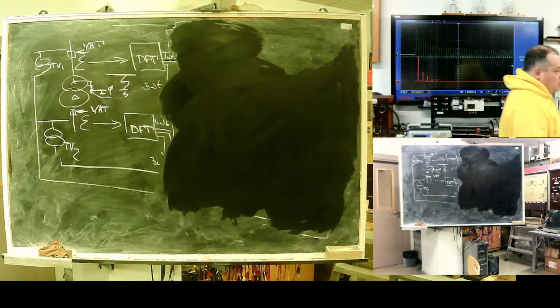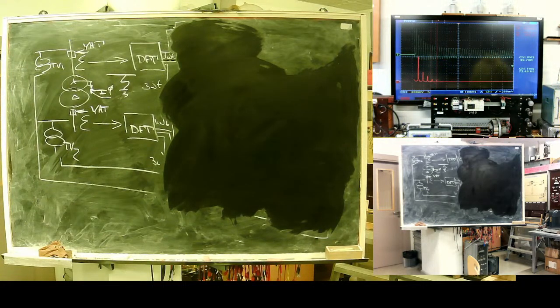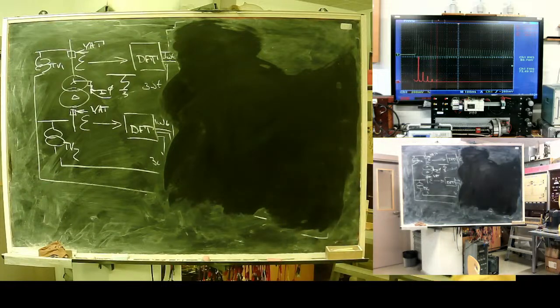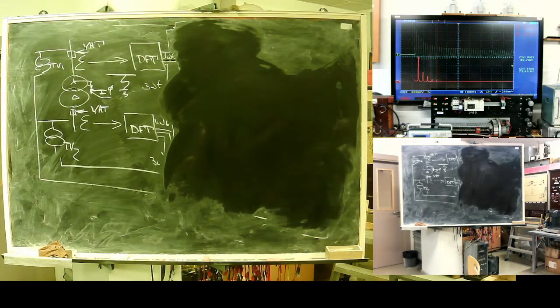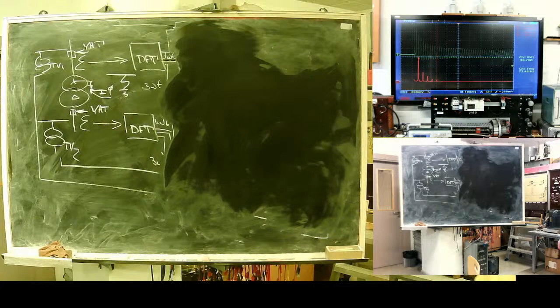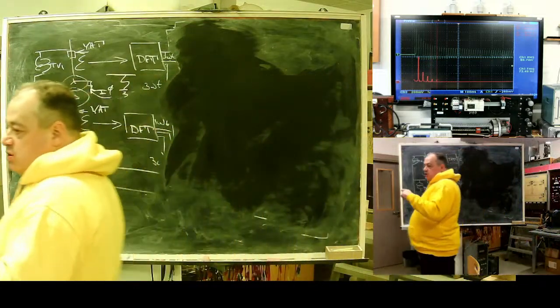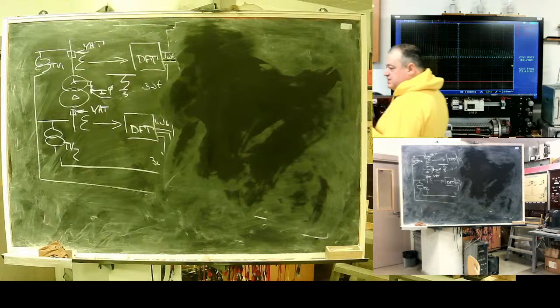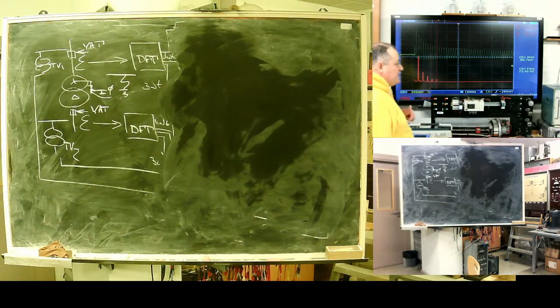Because normal network load is symmetric, a very low level of negative sequence can be observed. But internal faults in the transformer introduce asymmetry between legs, because a short-circuited winding produces flux oriented against the main flux. And on the peak areas, it leaves the faulted leg magnetized differently.